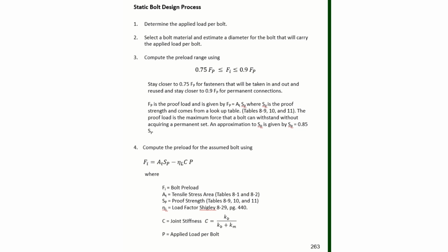And if that's made of mild steel, then I can get an idea of where I need to be to estimate the diameter of the bolt based on the actual applied load that I have for the situation I'm looking at. So you need to get your reference point and remember a reference that you can use throughout your career.